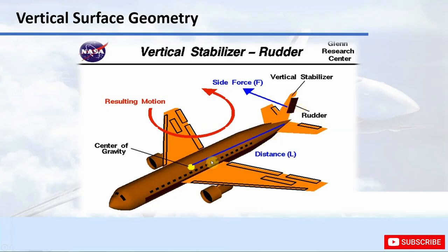And also we're going again to consider the distance of the vertical stabilizer from the center of gravity, which is important for our estimations. And I must mention that the vertical stabilizer is basically stabilizing the aircraft in the rolling moment. So it stabilizes that the aircraft does not roll freely, okay? And on the other side, with the rudder you can actually control the rolling moment, in which direction you would like your aircraft to go, but that topic we're going to dig into in the next sections. So today we're only going to estimate the characteristics of our vertical stabilizer, or our vertical surface.